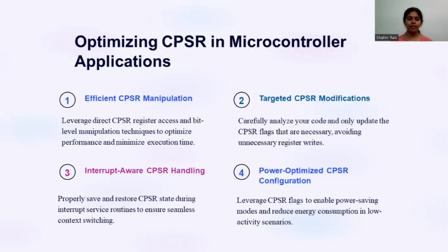Interrupt aware CPSR handling: properly save and restore CPSR state during interrupt service routines to ensure seamless context switching. Power optimized CPSR configuration: leverage CPSR flags to enable power saving modes and reduce energy consumption in low activity scenarios.